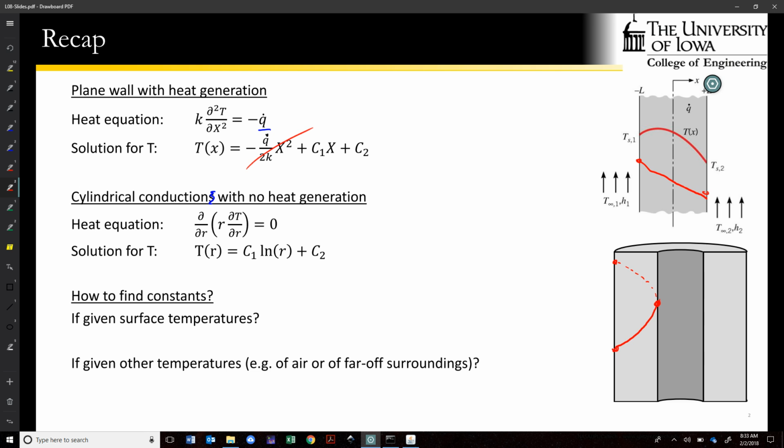In the cylindrical case, though, we still have all the heat that's entering the solid from this inner diameter here. All of that has to come out because the surface area at the outside is bigger, right? Then that heat gets spread out. So our Q double prime, our heat flux, decreases, and that's reflected by the fact that the slope here is higher, meaning Fourier's law tells us that heat flux is higher, and it decreases as we move towards the outside.